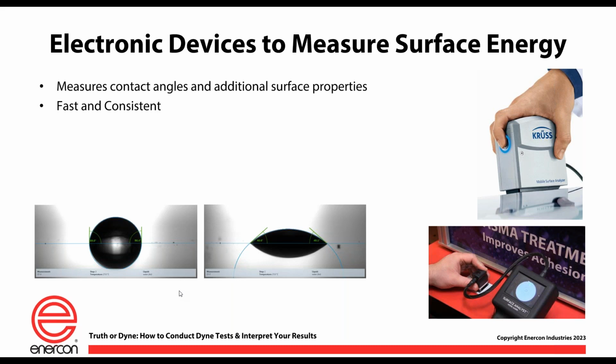Now you can make a connection by saying, I get a good result on a 40 dyne, which also gave me a contact angle of 35, and I had a peel adhesion number of so much, and those three columns can line up time after time, and that would be great. You can do that, but really the values stand on their own. So I would encourage you, if you decide to do this, that's a great method. You're really putting yourself in a good position going forward with good process information and best practices in terms of supporting your customer, your end user, with a great product.